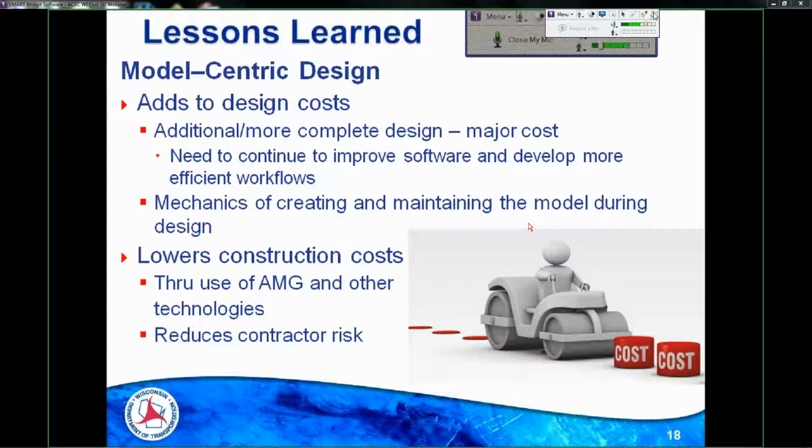Another example, something that some contractors want to do differently, is undercutting our slope areas for topsoil, okay? So we show our design models the exact same way we show our cross sections with proposed ground at the top surface, okay? But you could show a subgrade, allowing for the thickness of topsoil that you're going to put out there. And some contractors are doing that. So they're actually modifying the surfaces, in that case reconfiguring or restructuring those surface models to suit their operations.